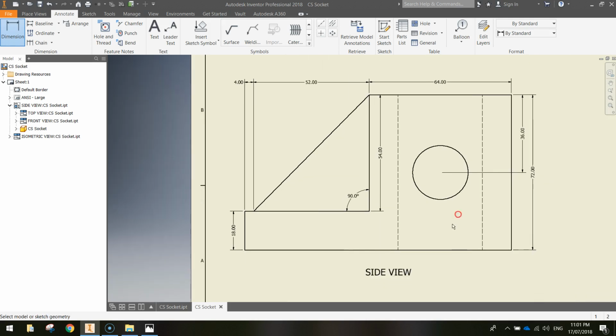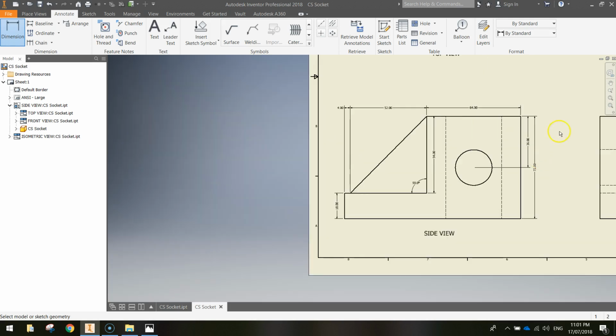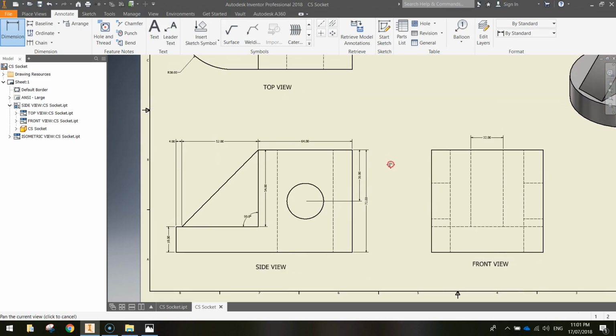Okay, if you wanted to, you could put on the dimension that runs all the way along the bottom, which is 120 mil, but because we have all these dimensions at the top, we don't need to do that. Okay, remember we don't duplicate dimensions, just put in the bare minimum so people can recreate this shape if need be. Alright, so that is all our dimensions sorted.